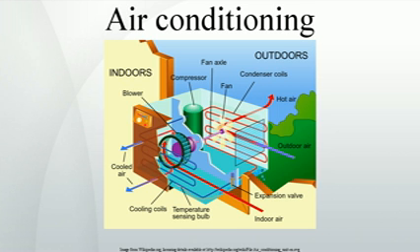This is due to the problem of ice forming on the outdoor unit's heat exchanger coil, which blocks airflow over the coil. To compensate for this, the heat pump system must temporarily switch back into the regular air conditioning mode to switch the outdoor evaporator coil back to being the condenser coil, so that it can heat up and defrost. A heat pump system will therefore have a form of electric resistance heating in the indoor air path that is activated only in this mode in order to compensate for the temporary indoor air cooling, which would otherwise be uncomfortable